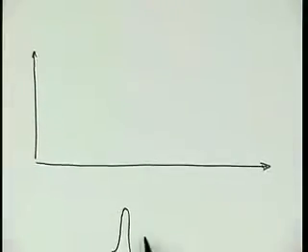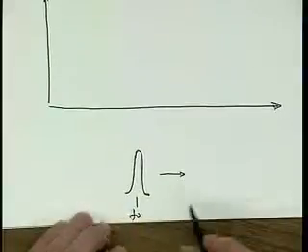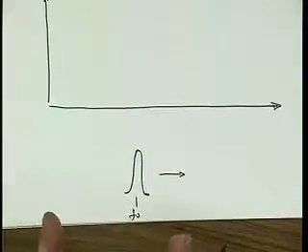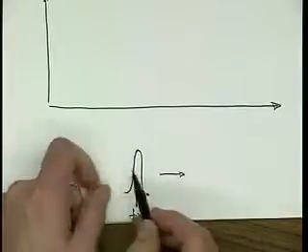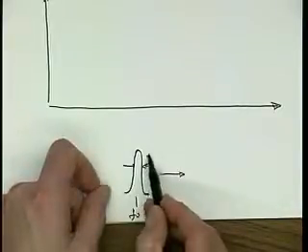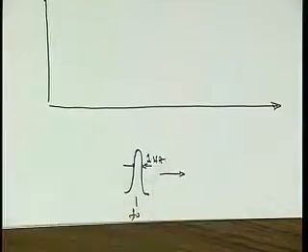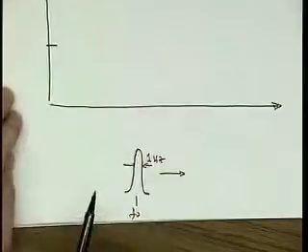And then after that filter comes a power meter, and it measures the total power that comes through this filter that, for example, has a 1 Hertz bandwidth. So if we take a spectrum analyzer, put it across our resistor, and then sweep it, we first find out how much noise we have in the band from 0 to 1 Hertz, and we mark it here.